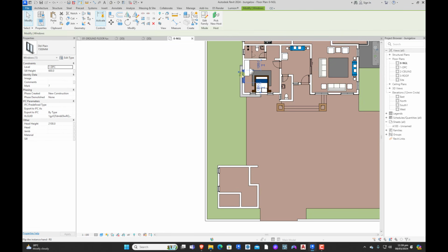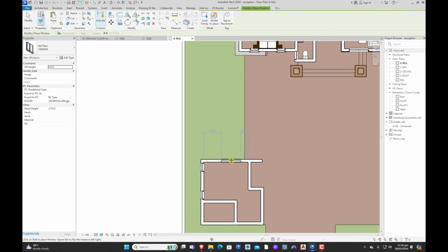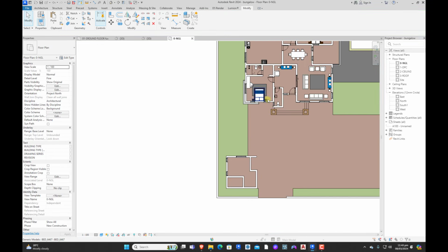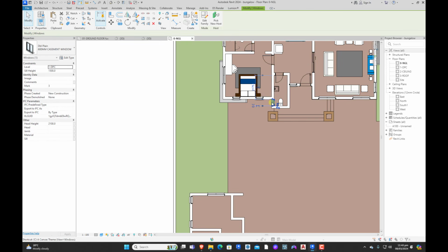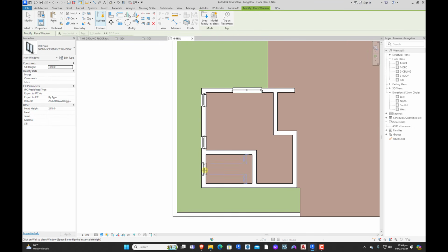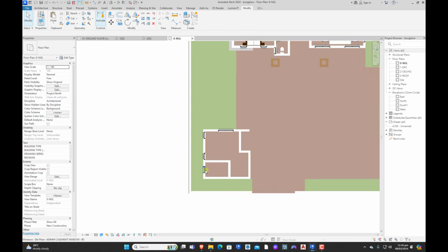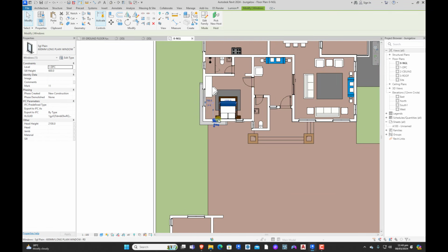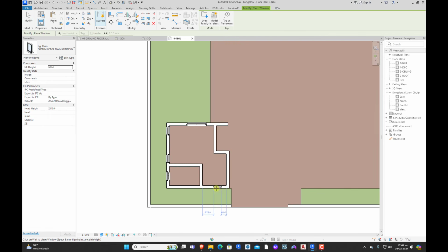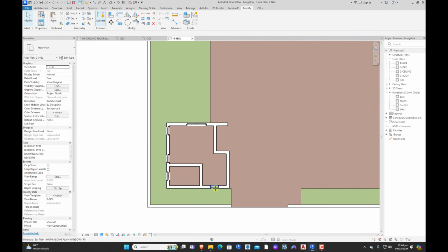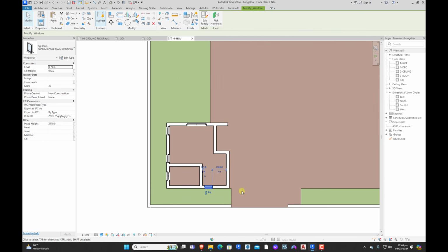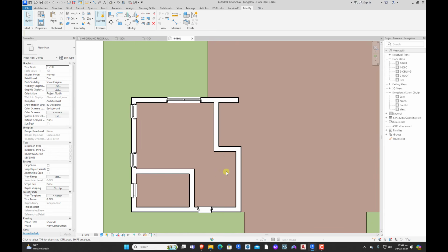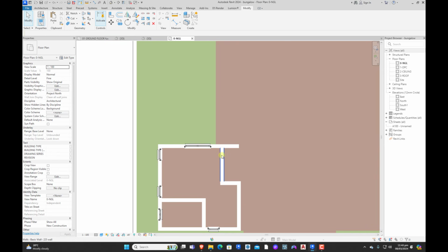Then you can use this one, CS, to create similar, place another one here. Then the toilet window, CS, to create similar, and place one right here. Alright. Then you can also place one long window at this corner as well. Yes, you can place this here. So you can use this portion for the wardrobe. Alright, so this is good.